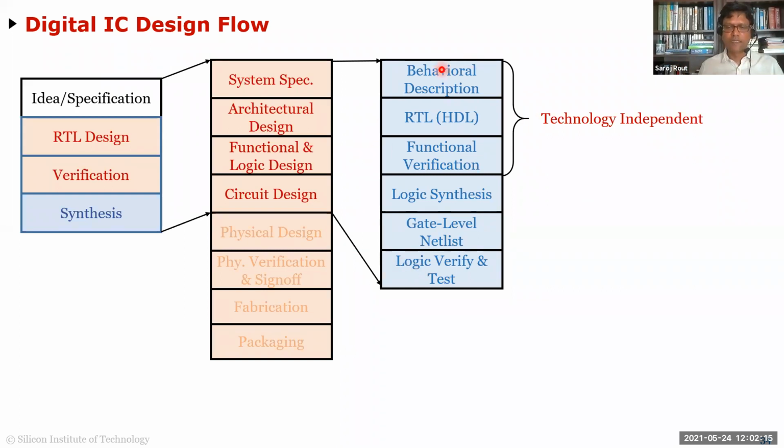And as I was explaining in the previous slide, your behavioral description can be done purely in Verilog or SystemVerilog or SystemC, MATLAB, Simulink, any programming language you can use to do a behavioral description. And that's obviously technology independent because you don't need to know what technology you're finally going to go into. You're just writing basically computer programs to write your behavioral code. Your RTL is the register transfer language, or whatever is your hardware description language.